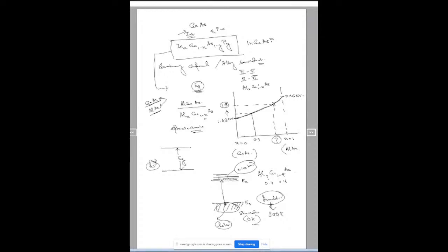But for a macroscopic description in semiconductor device analysis, we normally do a macroscopic analysis. Macroscopic analysis means we do not apply quantum mechanics or go to the subatomic level to investigate what is happening. For electronics engineers, it is important that we analyze by terminal behavior, like we apply a voltage across this device and see how much current is flowing. This kind of description is a macroscopic description.